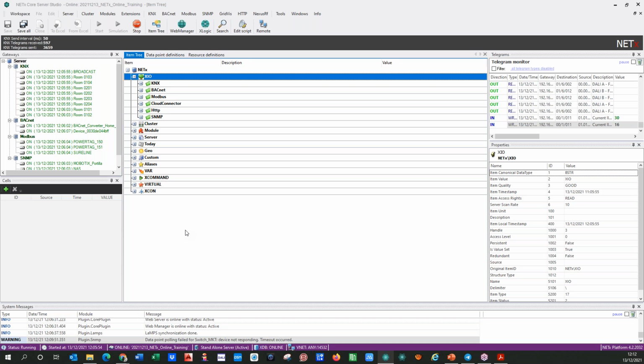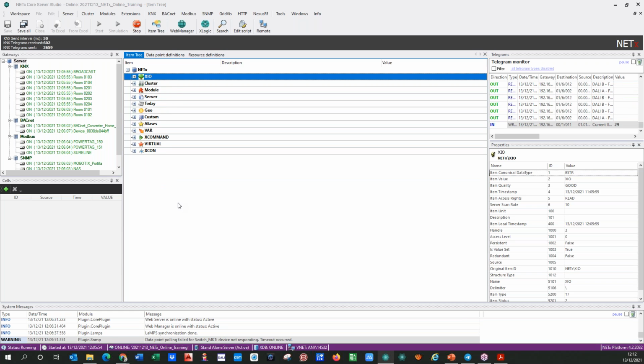To finish this second session, we can see there are a lot of protocols, but we need one more, OPC. As a client, we can also get information from different OPC servers. An OPC server is commonly used when you don't have a native driver for specific protocols. For example, for fire alarm systems it is typical, or old automation systems, you may need to convert this to OPC.